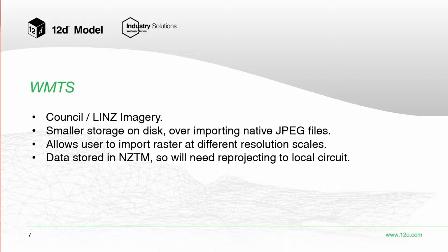One downside is that the data is stored in NZTM. We do need to reproject that location polygon from local circuit to NZTM before we actually import the aerial photography. Then we have to reproject it back into local circuit.